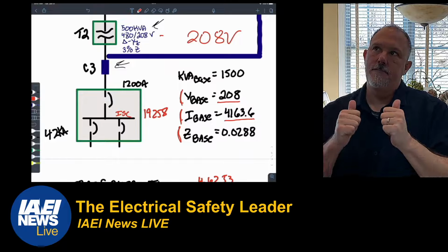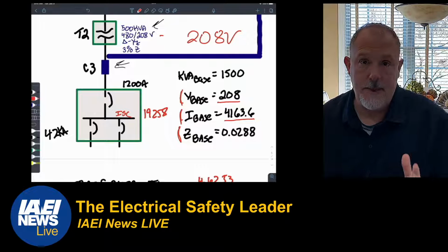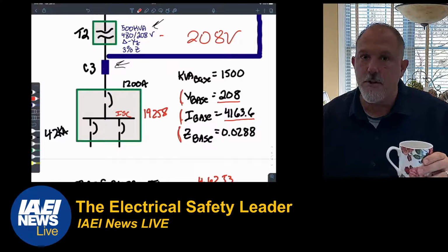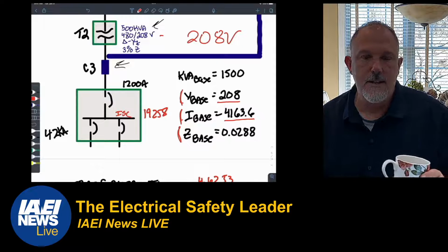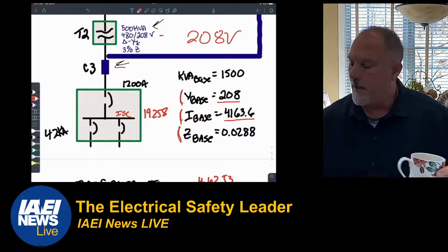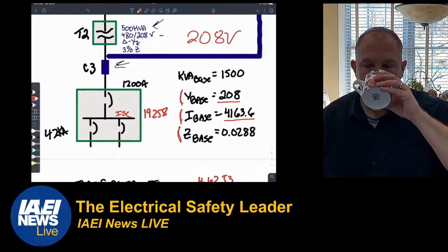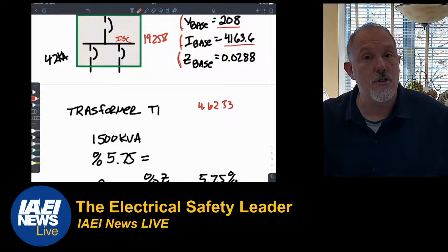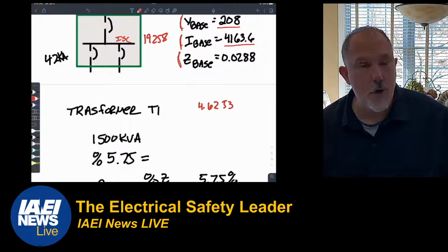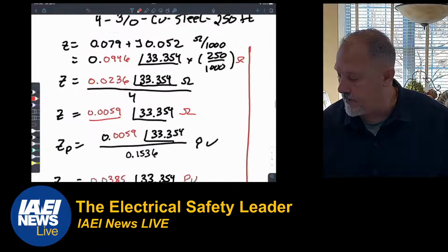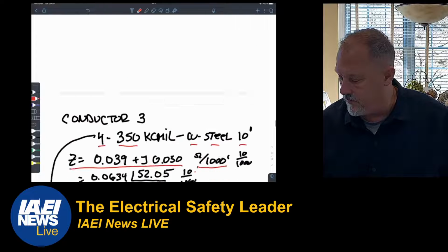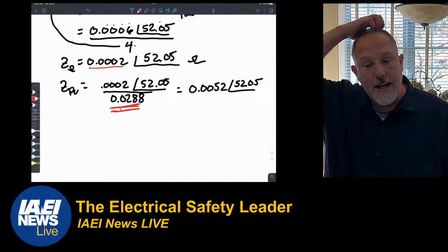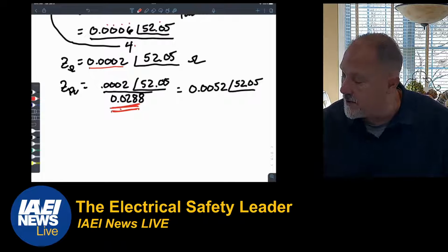I would typically screw that up. It just escaped me. I mean, you're nervous, you're on an exam, you gotta relax and just think about the basic equations. All right, so my new Z base at the 208 volt level is 0.0288. So let's go back down. So that is why I used 0.0288 to get a 0.0052.